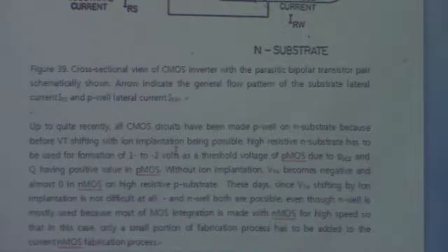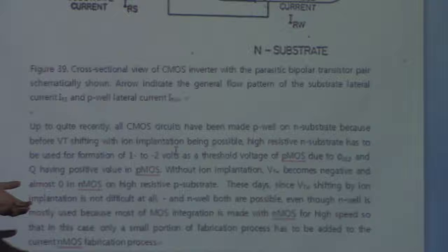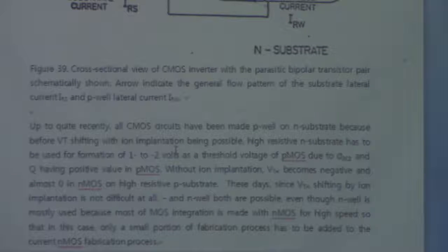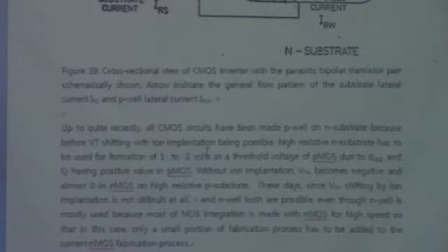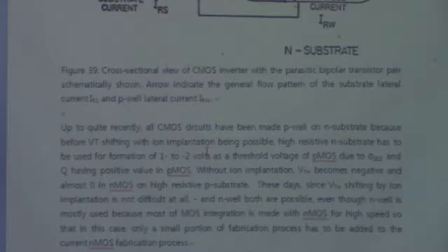So what is the problem with this latch-up? The real problem is not the current itself, but the heat which is going to be generated by the Joule heating through this current. The current level is very high, and each tiny CMOS, tens or hundreds of thousands of them located in the same place, each generates Joule heating through this latch-up current, then it's melted down.